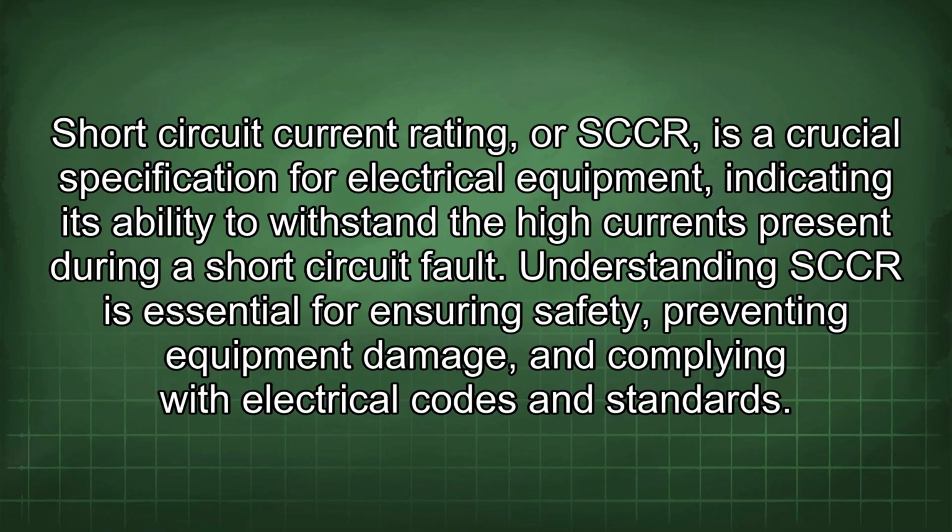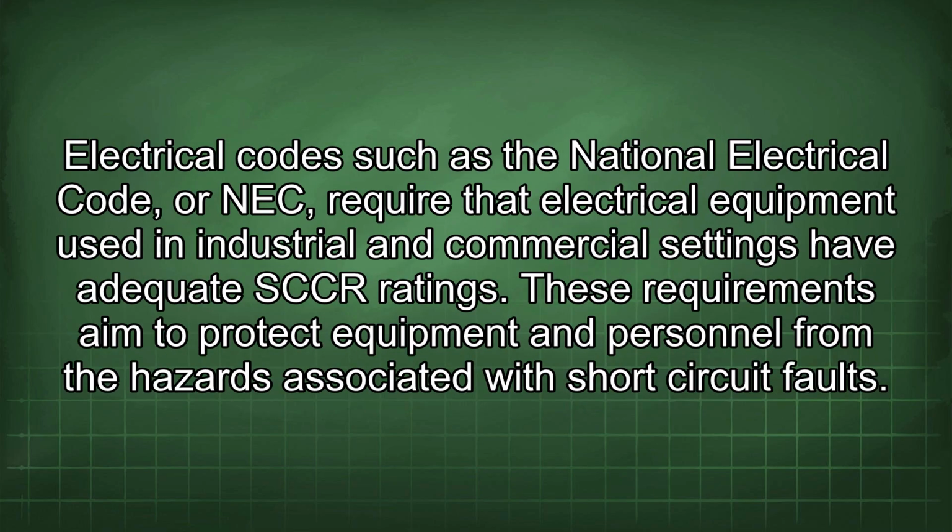Short circuit current rating, or SCCR, is a crucial specification for electrical equipment, indicating its ability to withstand the high currents present during a short circuit fault. Understanding SCCR is essential for ensuring safety, preventing equipment damage, and complying with electrical codes and standards. Electrical codes such as the National Electrical Code, or NEC, require that electrical equipment used in industrial and commercial settings have adequate SCCR ratings. These requirements aim to protect equipment and personnel from the hazards associated with short-circuit faults.